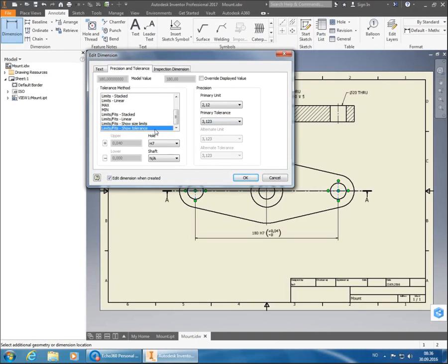let's see. Well, an H7 is exactly 0.4, I can see. There. An H8, as we can see, has 3 digits. If I now take this one back to just showing 2 digits, it has suddenly changed my tolerance there. So it's always wise to show all 3 digits when you are doing those ISO fits.